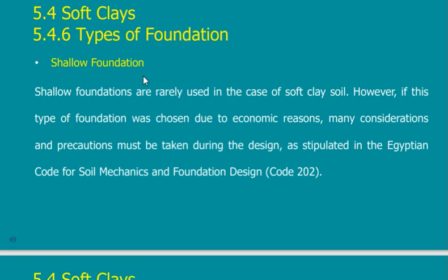But is it good for soft clay? No, it's not good for soft clay. I should not go to it unless I am forced to do it. Here, shallow foundations are rarely used in case of soft clay. Rarely. But if I have to use them, then I will have to take additional precautions.